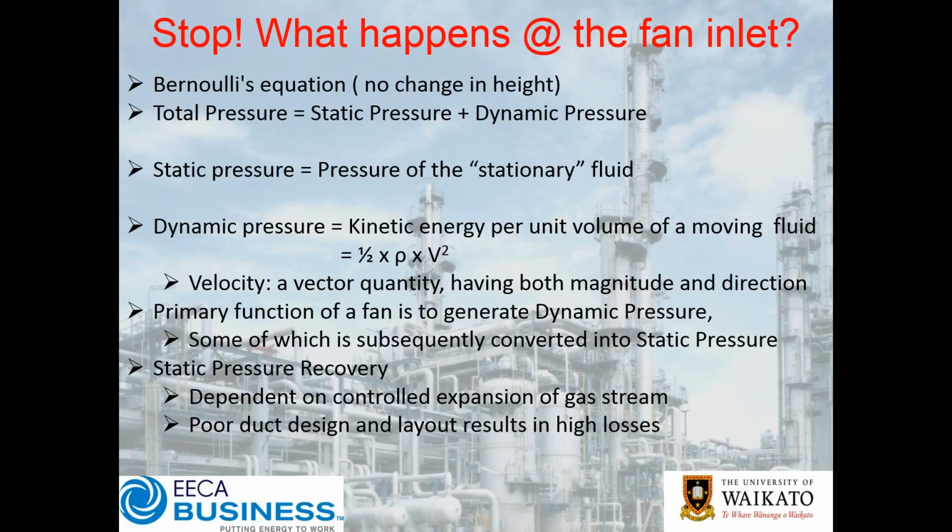So the primary function of the fan is to generate this dynamic pressure, and then subsequently the primary requirement of our fan housing and fan outlet, and then the subsequent ducting, is to maximize the conversion of that dynamic pressure into static pressure. Static pressure recovery is going to be dependent on how we control the expansion of the gas stream, and if we have poor duct design and poor layout, it's going to have a very low static pressure recovery and a whole lot of additional parasitic losses, which means that our fan is going to have to work that much harder.